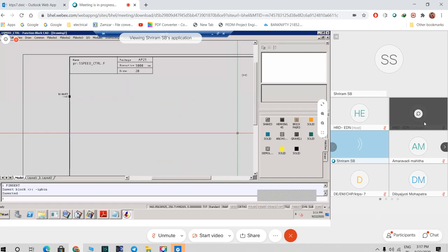Okay, ANA and ANA event, what is the difference? Basically, the event data type will give the value as well as the time change. That is, at the point where the value has changed, time stamping will be there in addition to the value. That is the main difference between ANA and ANA event data types. But usually we don't use the ANA event data type. We use mainly binary event only, because we don't use any time stamping for analog values. So in our logics, usually you may see ANA or binary event. These three are the main data types which are used. Okay, now I have created this interface port.